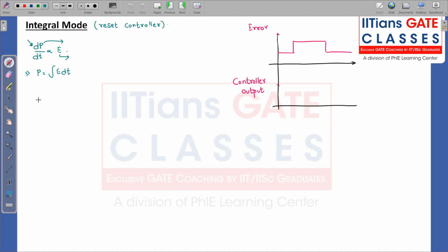So my governing equation is this. Now, if I remove this proportionality sign, it is going to be Ki into E. Let me write this as EI to differentiate that this is the I controller. Now, what is this Ki basically? Ki is equal to 1 by Ti, where this Ti is integral time, also called reset time. And this Ki is called the integral constant.